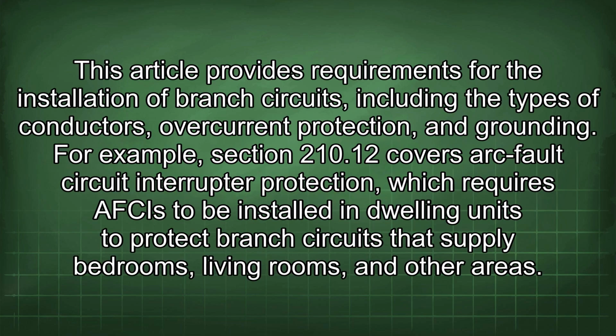This article provides requirements for the installation of branch circuits, including the types of conductors, overcurrent protection, and grounding. For example, Section 210.12 covers arc fault circuit interrupter protection, which requires AFCI protection to be installed in dwelling units to protect branch circuits that supply bedrooms, living rooms, and other areas.